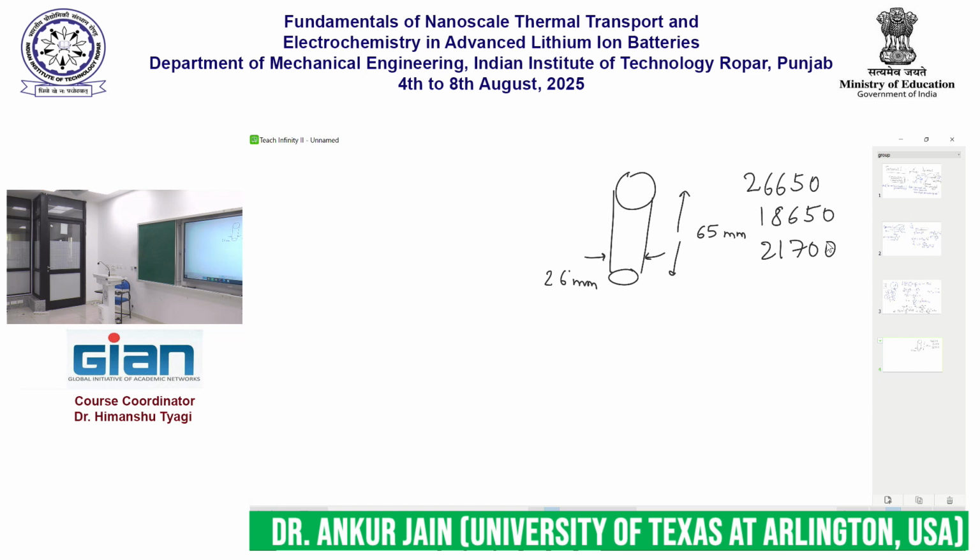The way to read this is that the first two digits refer to the diameter in millimeters, and the last three refer to the height of the cell, 65 millimeters. A typical electric car like the Tesla has about 10,000 such cells.